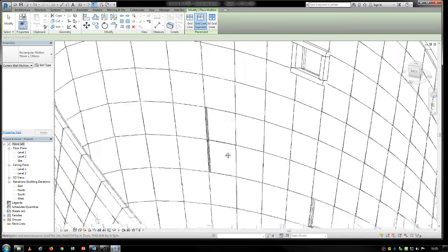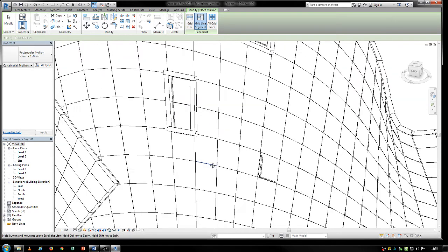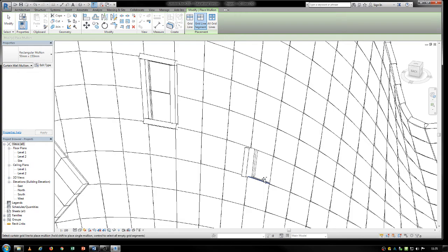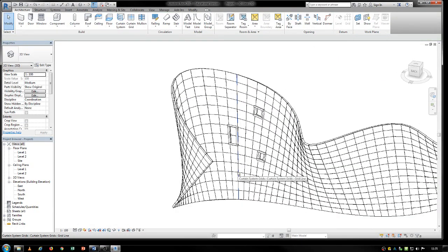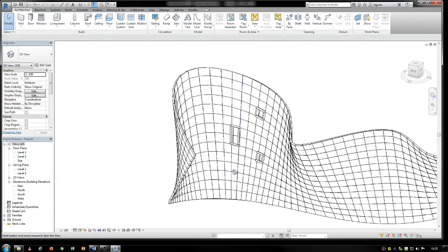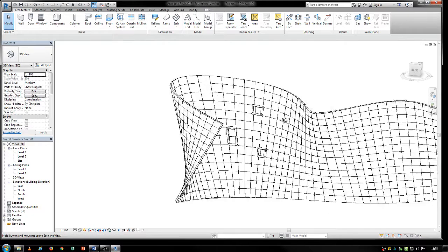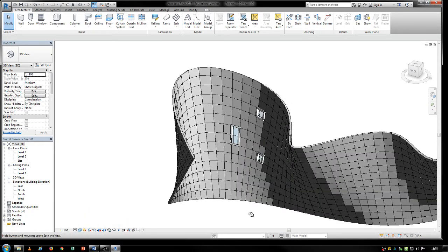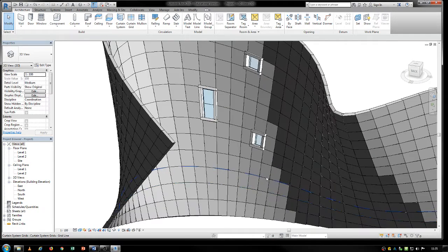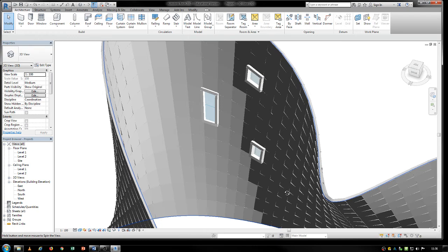This is a very small scale, so that's why it's looking a bit weird, but you could basically go back in and join these mullions and work with that a little bit. That's kind of another way of making that wall, because in real life, maybe it will be a modular system with all these panels you want to put in. Some of them will be glass, and some of them would be the wall panel. So that's how you would maybe deal with that system, instead of having the whole thing be this curtain wall,